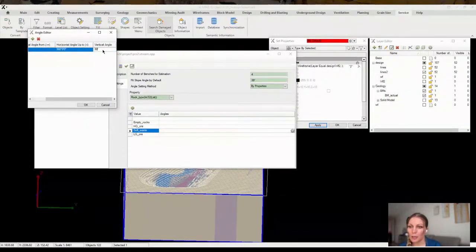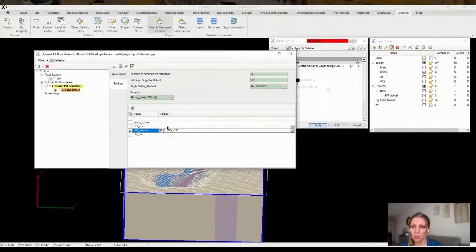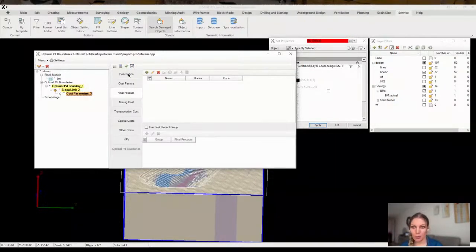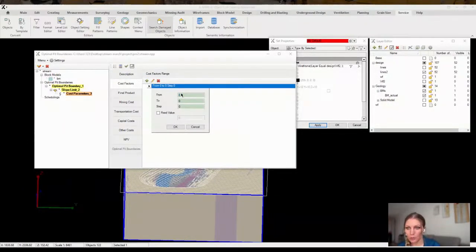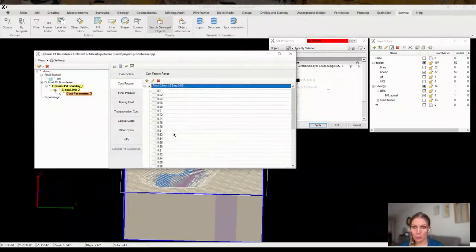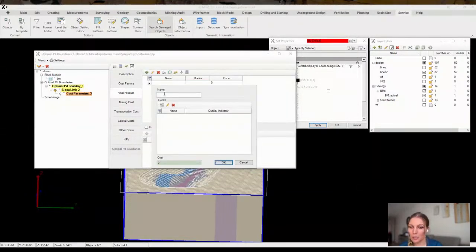We'll also create a subdirectory in the project tree and choose the relevant block model for further use. Keep in mind that although multiple block models can be utilized in the project, only one can be involved in the calculation at a time. And next, we'll configure the indicators for the resulting pit angles. For rocks, we'll use 39 degrees, and for soft rocks, we'll use 30 degrees.